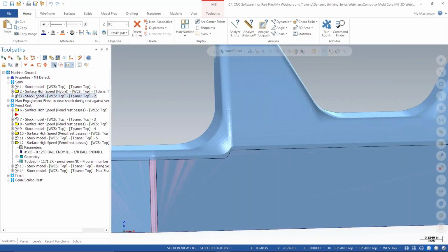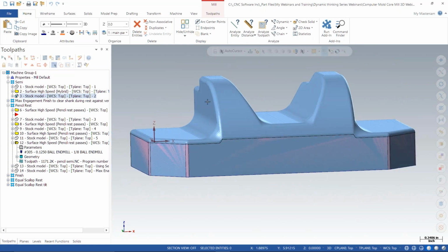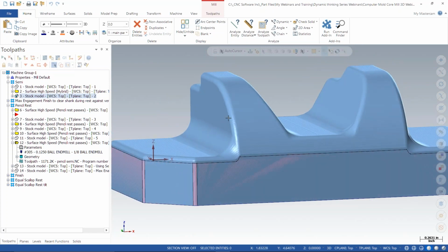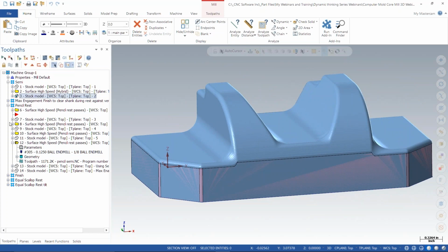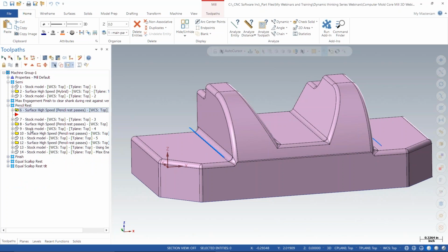Because this semi is 5 thou material heavy. There's 5 thou on this right now. And I semied this all the way down and I left 7. Why did I leave 7? Because this is a vertical wall and I wanted to stay away from it a couple thou and just not hit it. But again, don't question the sample that we're using. It's the concept of digging in and digging in and digging in and digging in.